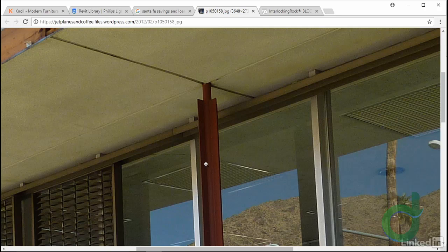What we'll see a lot of times is when we get a round form and a flat form pretty close, we actually get a light bleed in a rendering, and this is terrible in a real-time application where we've baked and simulated the lighting down to a pretty good degree. We tend to get a little bit of light showing right here where it should be all in darkness and all in ambient occlusion if we're running it. Therefore, I'm going to take a look at this family and make sure that this column is nice and tight and closed up.